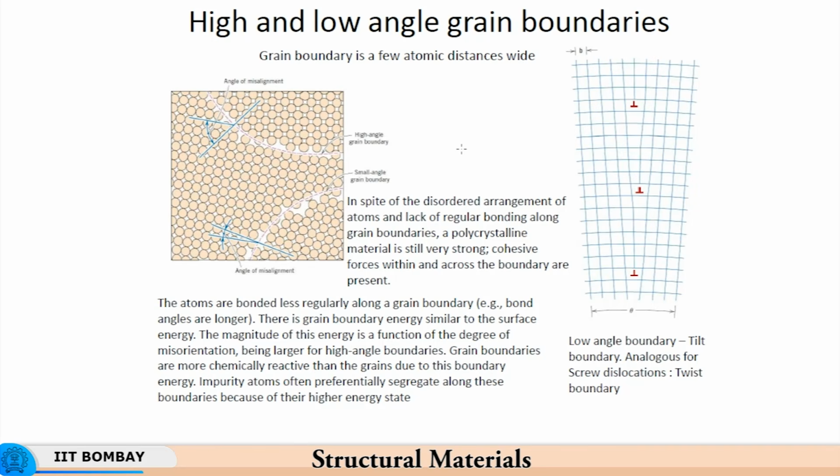I was talking about orientation of crystals in specific directions. So one can generate these orientations in crystals, in planes relative to the direction of loading, by using an appropriate manufacturing route, an appropriate manufacturing process. The reason this happens is because you manage the generation of defects properly by subjecting the material to appropriate amounts of stress and strain.